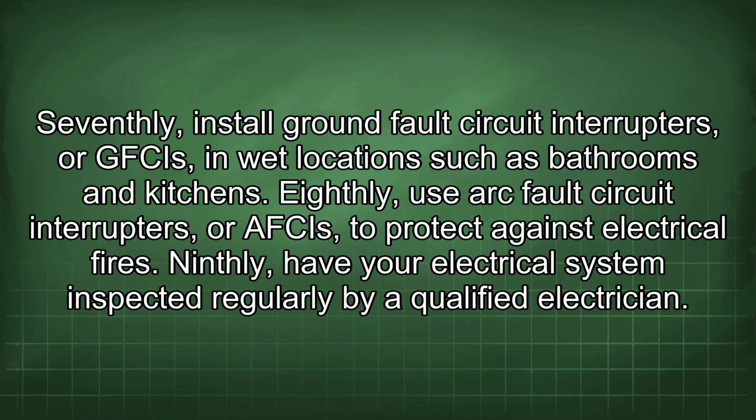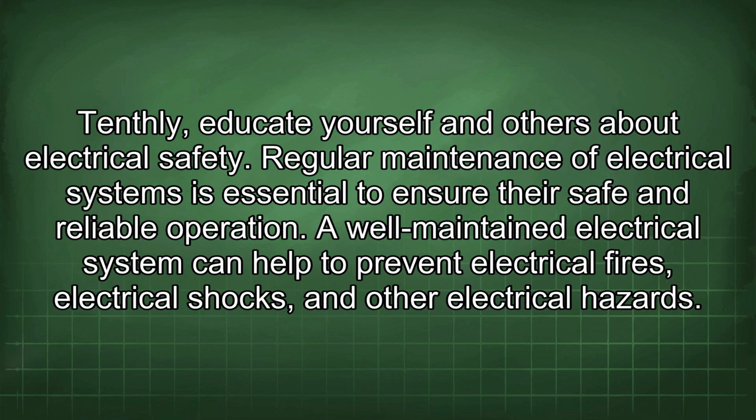Seventhly, install ground fault circuit interrupters, or GFCIs, in wet locations such as bathrooms and kitchens. Eighthly, use arc fault circuit interrupters, or AFCIs, to protect against electrical fires. Ninthly, have your electrical system inspected regularly by a qualified electrician. Tenthly, educate yourself and others about electrical safety.